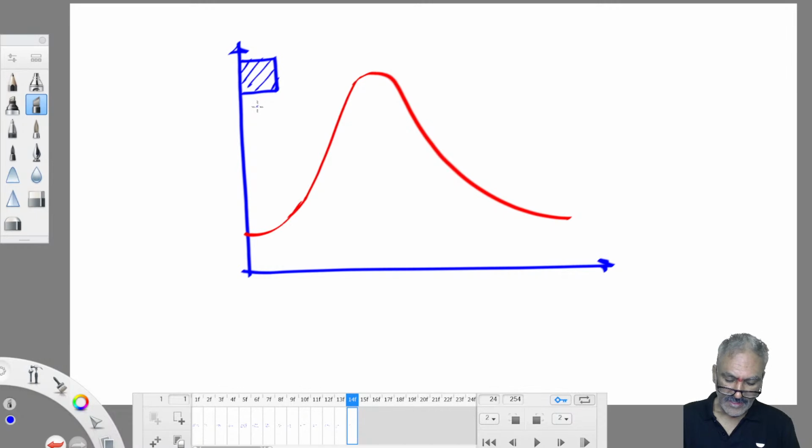Storm information we give in the form of a hyetograph, a plot between intensity of rainfall versus time. So, what is the time? Duration of storm. Let us assume duration of storm is D. D hours rain has occurred, right? The D hours storm produces this hydrograph. Therefore, we call it a D hour storm hydrograph or D hour flood hydrograph. So, I will take it as D.